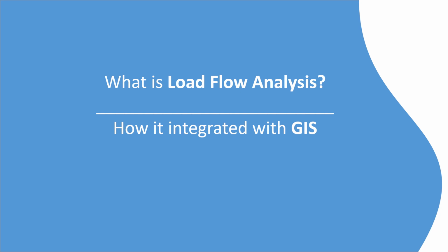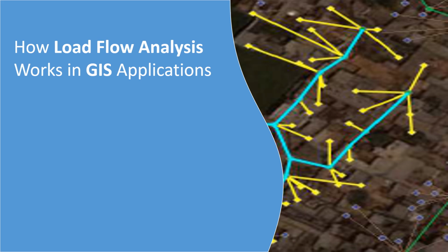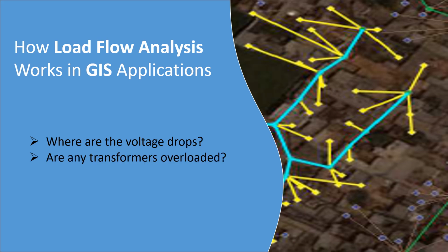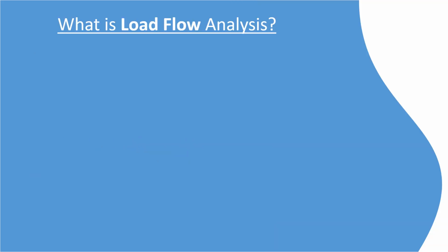Hi guys, in this video we'll see what load flow analysis is and how it is integrated with geographical information systems. By using load flow analysis with a GIS application, we can identify where the voltage drops are, whether any transformers are overloaded, and how balanced the system is.